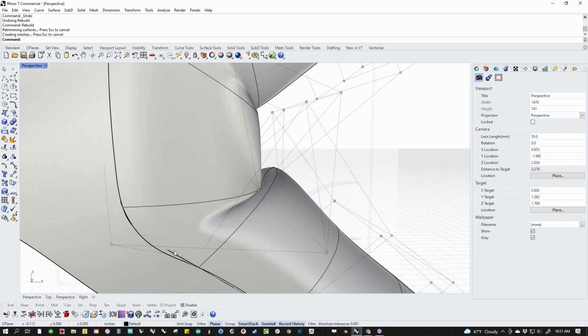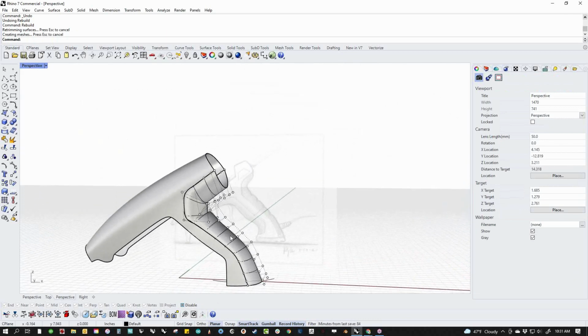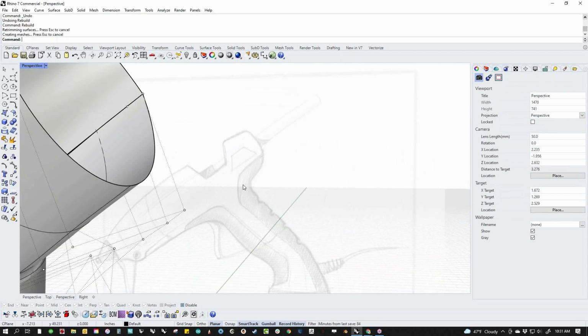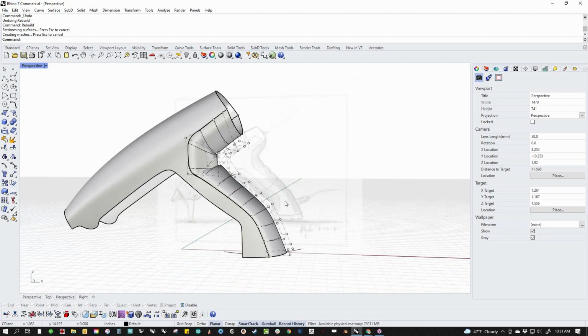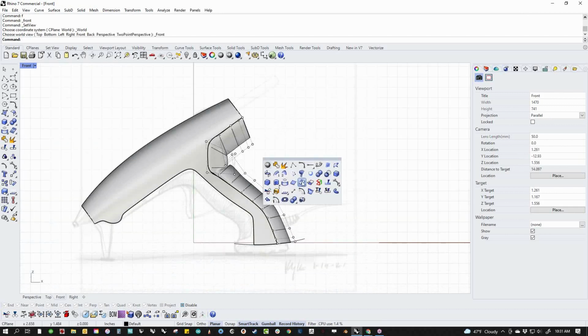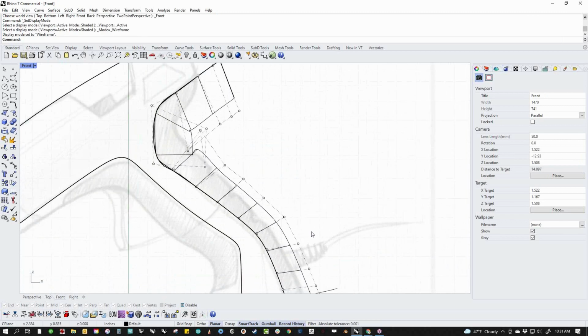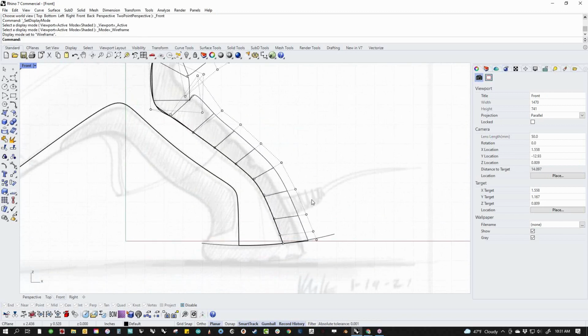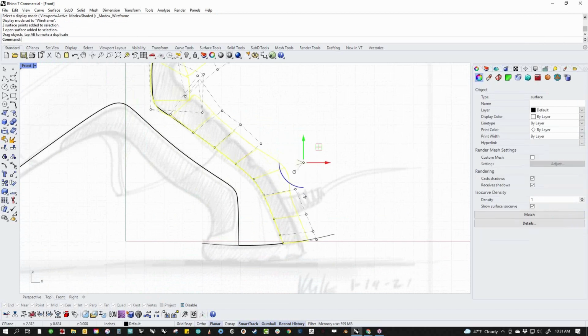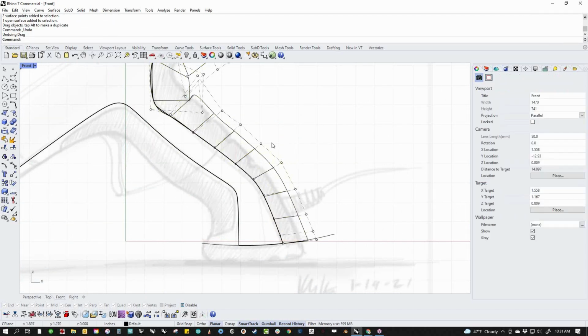And you're saying to yourself, wait a minute, that seems insane, because now very clearly this surface does not join with this surface anymore. Well, so what? There's a gap here, there's a step, there's a material break here anyways that we have an opportunity to blend over, so who cares? Let's fix what's here, and let's make this surface do what we want it to do, and then we'll worry about how it connects back with the rest of the model later.